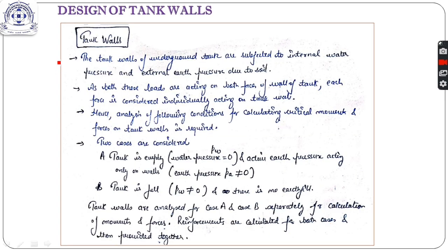Now I'll be explaining how we design tank walls. The long walls and short walls are designed in a similar way as we studied in the previous case, but here there is one very important difference. As I told you, the tank wall is subjected to two loads. One is water pressure, and the outside face is subjected to the earth pressure. So we have to consider both these loads.